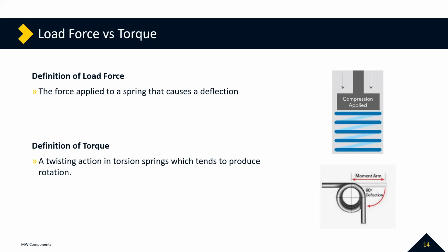Whereas with a torque, basically centered around a torsion spring, you are bending, creating a moment about a specific axis and picking up an angular deflection. You're still deflecting, but you're not moving vertically or horizontally. You're deflecting angularly, picking up that moment or that torque.